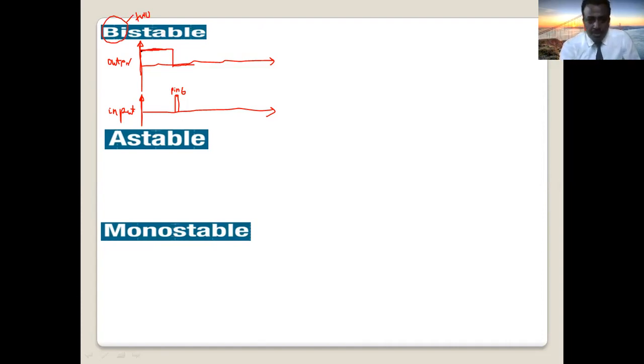So look here, the output of this timer is high state. It is on, so it is stable, right? Until we apply what? When you apply this input at pin number 6, the output changes from high to low state. Now what will happen? Again, this state is also stable. Stable means, as I said, it will not change. It remains the same unless you apply an external input. If you are not applying one, it remains off.